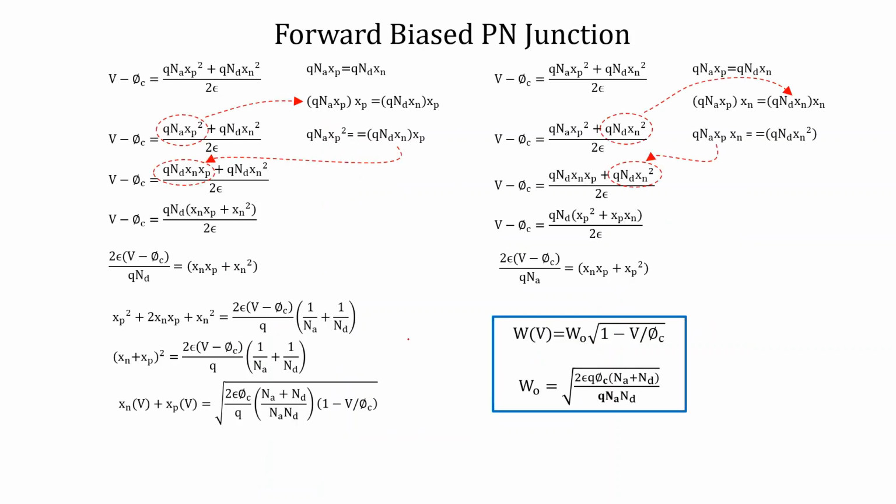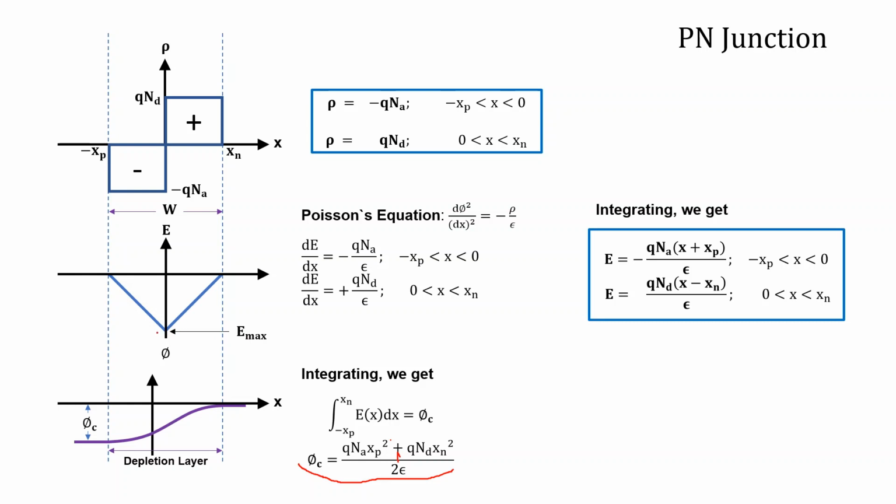Okay, that means what is Emax? Emax is the electric field which is maximum at the PN junction and reduces as we move towards either side. So if you forward bias by this voltage, Emax reduces, up to let us say here, and also the width of the junction reduces.